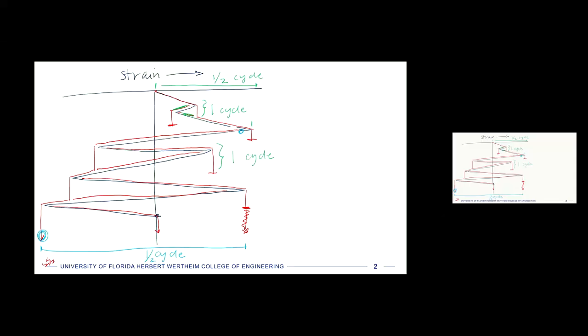If you look at the decreasing strain there, it was interrupted by our other rainflow we already accounted for. So it is a perfectly matched forward and reverse strain cycle there. The same happens for the next one here. It's fully reversing back and forth.